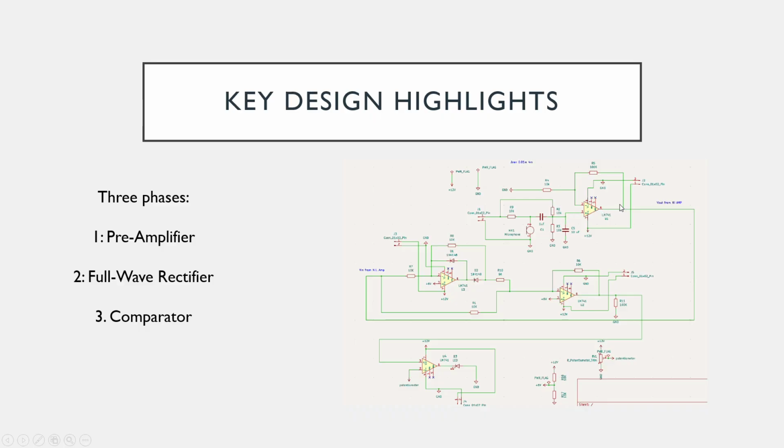Now it gets fed out at 10 times the input, and the reason we chose that is because whenever there's a voltage change in the microphone from when you speak into it, it's really small. So we decided to amplify it so that the comparator op amp would eventually be able to detect it.